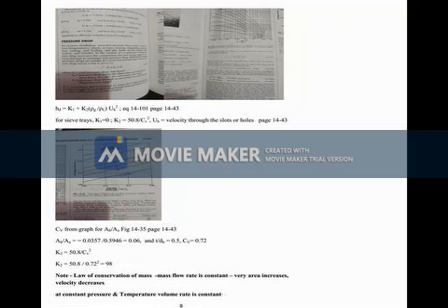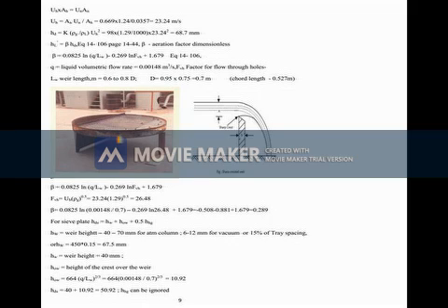What is CSB? Velocity is equal to CSB into (sigma by 20) raised to 0.2 into ((rho L minus rho G) by rho G) raised to 0.5, and you can calculate VNF. This is the flooding velocity, 1.54 meter per second. You assume 80% as the actual velocity, you will get 1.23 meter per second. Find out the area, that is the net area. Net area is the volumetric flow rate divided by velocity, you get 0.669.